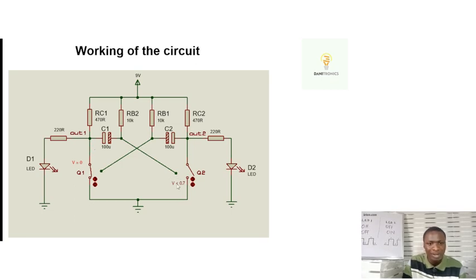And remember, when we have a voltage less than 0.7, the transistor is going to be off. And that's why this one goes off, because this one comes on. Since one closes, this one has to go off, because the voltage that it is going to see at this point is going to be less than 0.7. It's going to be 0, because this one has closed. And so once this one goes off, what then happens?